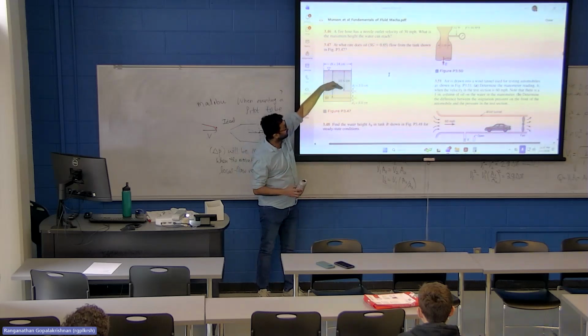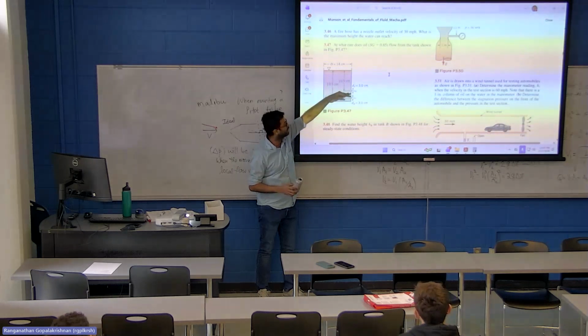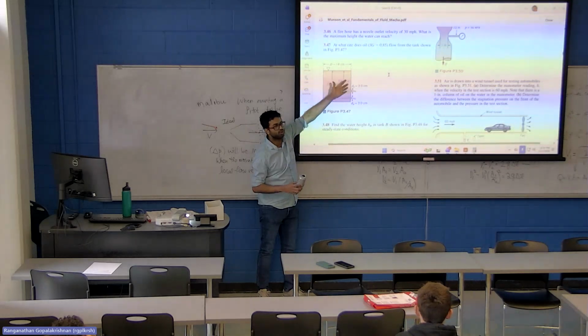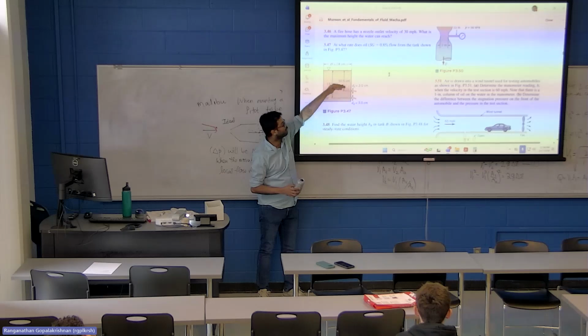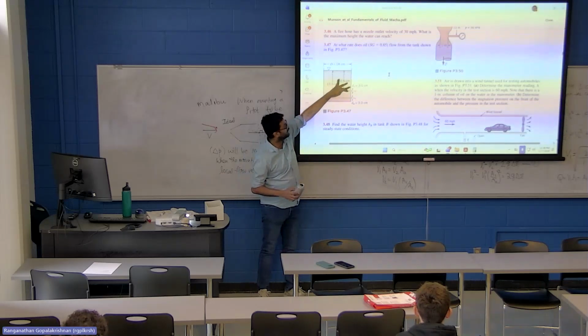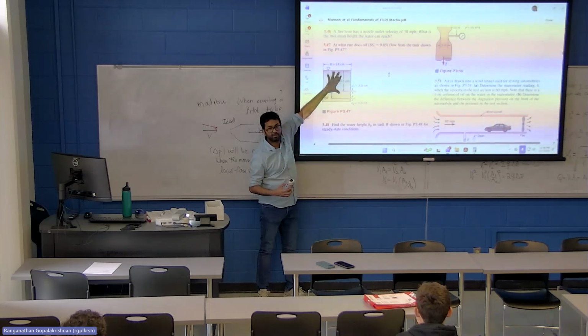Exactly, as the fluid drains out, the driving force gets weaker and weaker until it just goes away. So after the liquid level drops below this height, there is no more flow, right? So any estimate that you do is only driven by the instantaneous height of the liquid above that level.